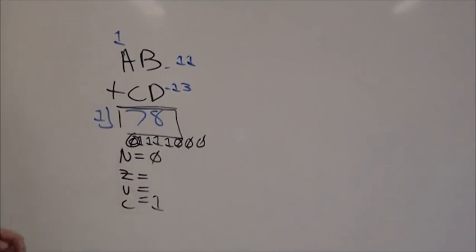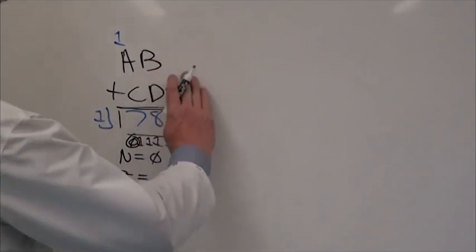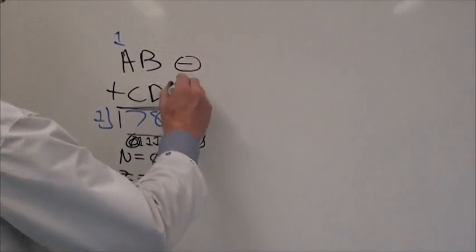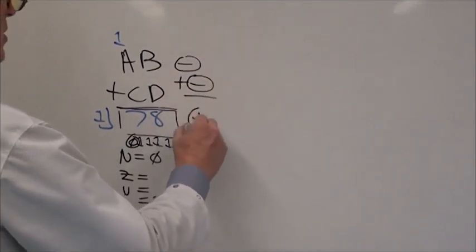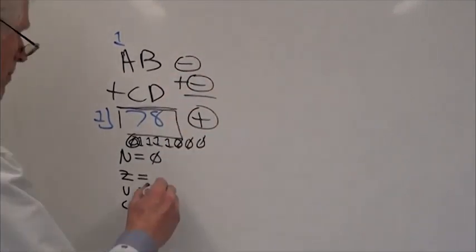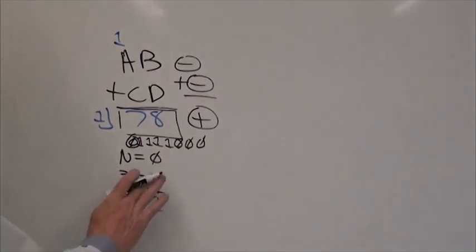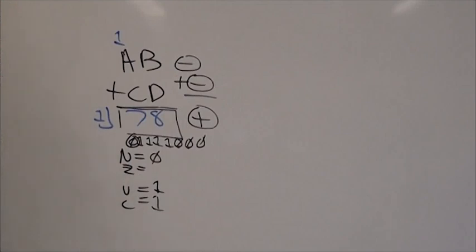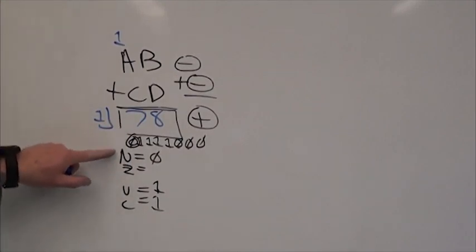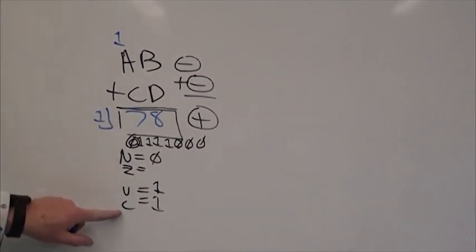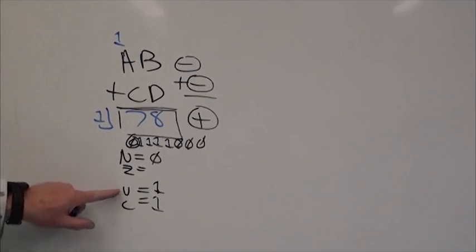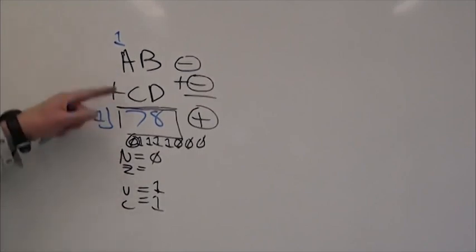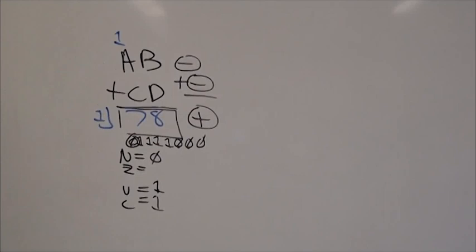Now we also see here we have a carry, or in our case it is carry because we're adding. And let's take a look at what kind of numbers we have here. This is a negative plus a negative, and strangely enough, it gave us a positive, so our v bit would indeed be 1. Now, here's the thing, for z, this is the MSB of the result, this is the carry, which in our case says unsigned overflow, signed overflow. This result is not valid in either number system.